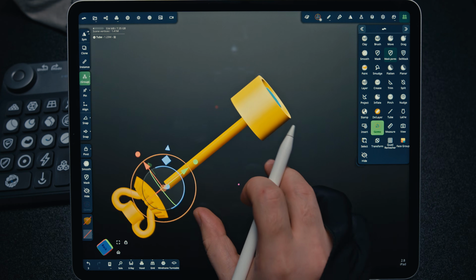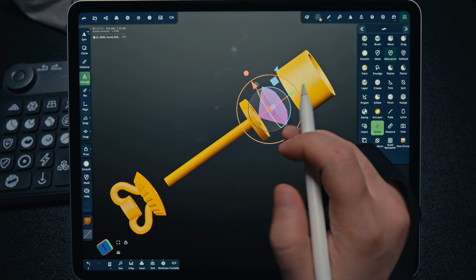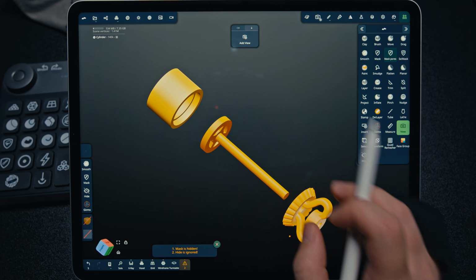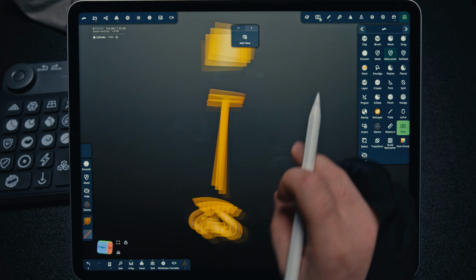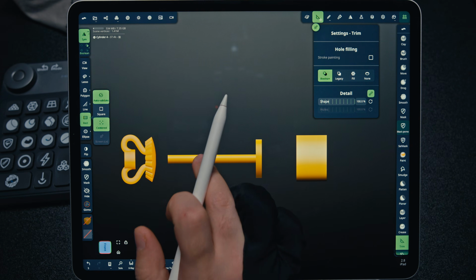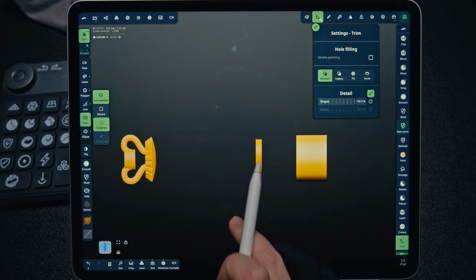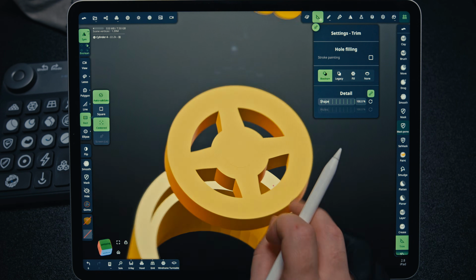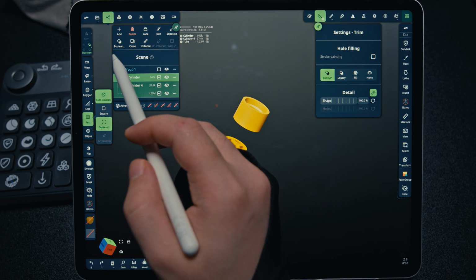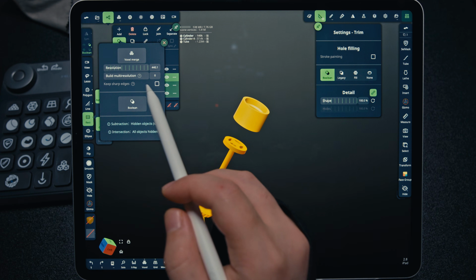Next, if we plan to print this, we need to separate the parts and delete the stone. As I mentioned earlier, some people find it more convenient to print such earrings without the post. But do not forget in that case to mark the center for the jeweler. But I won't do that. Next, we can press Boolean to get rid of internal intersections.